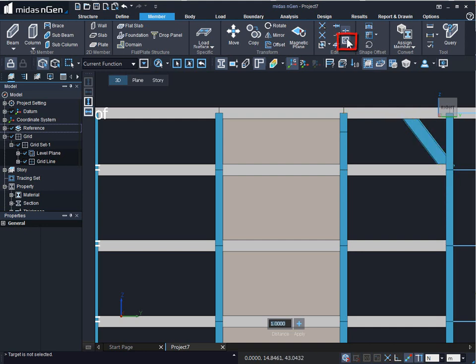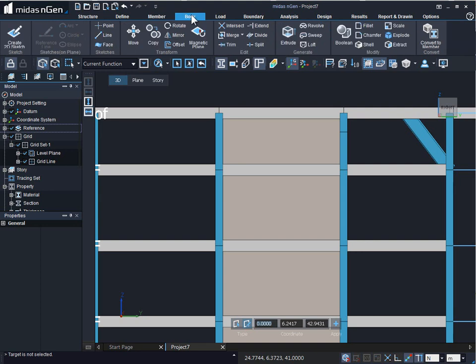Let us look at how to create openings. We can create openings on 2D members. For that there are two options. One is by select and the other is by draw. By select, we can select any members that are forming an opening in the 2D member, or we can select body lines. So let's say we have a body line, we're in the plane mode,